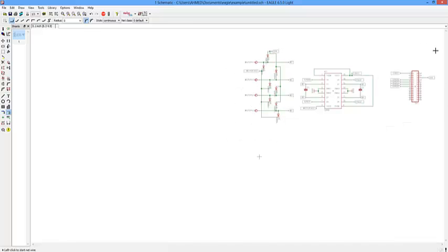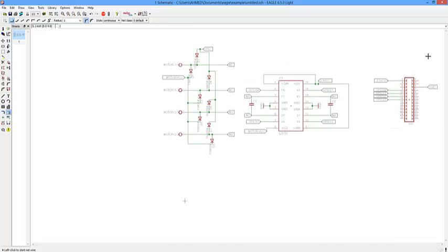Seems everything is okay. But what is missing still? Yeah, a source for VCC input to the H bridge to power the motors. That's a simple thing. Just get another screw terminal and that's it, and input your power to it, VCC and ground, and that's it.